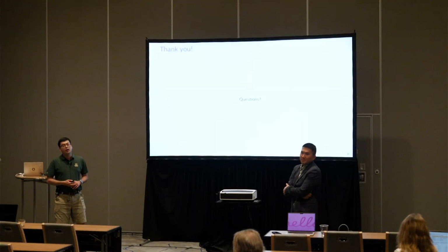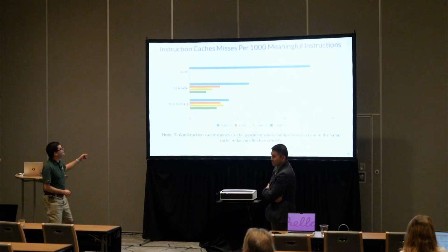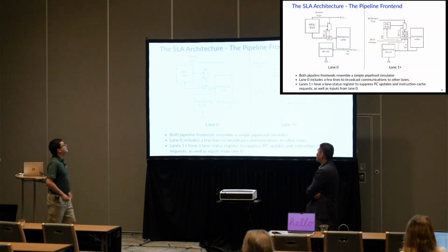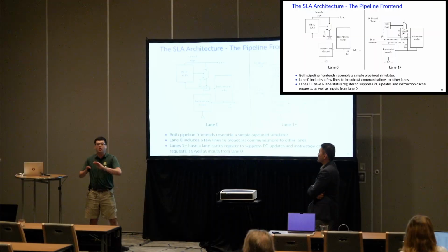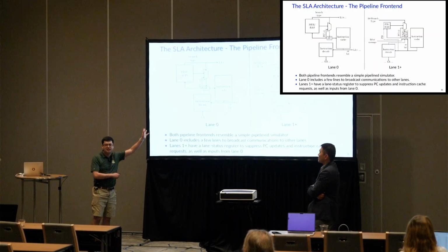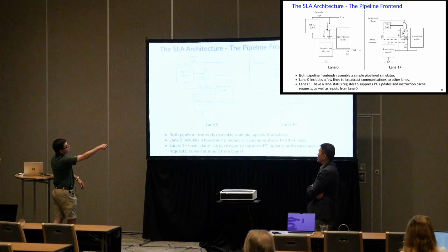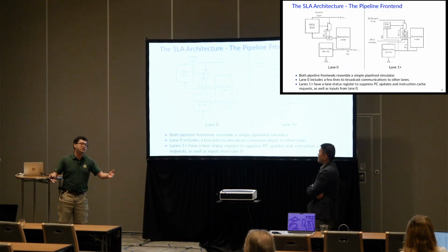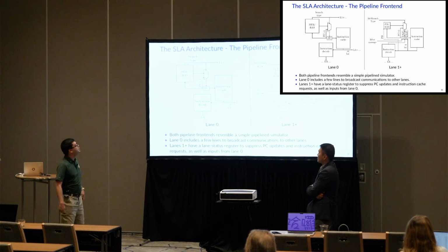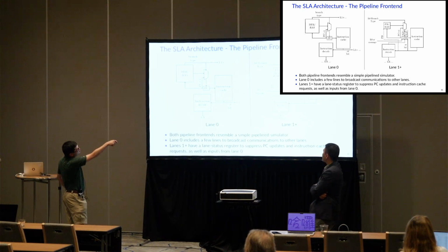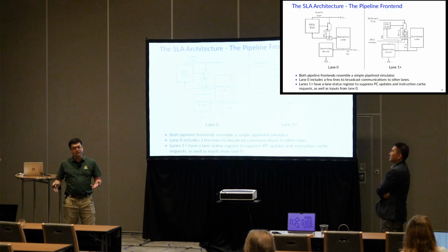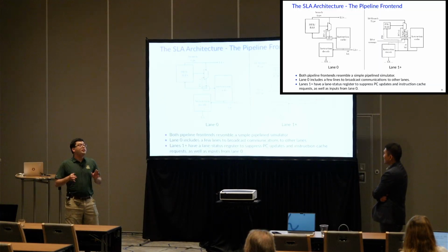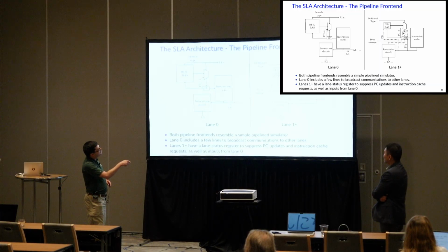Short version, let's go to the hardware and corresponding software. Lane 0 is the only lane that has access to the BTB. If I access the BTB in lane 0 and predict a taken branch, we broadcast that information to each lane. Say this is lane 1: there's an incoming signal from lane 0.